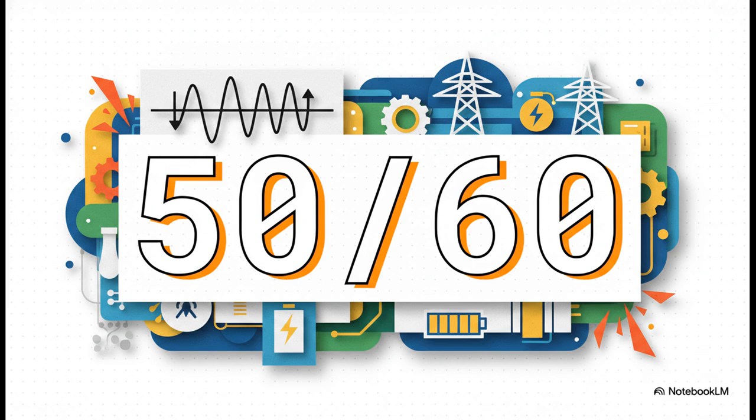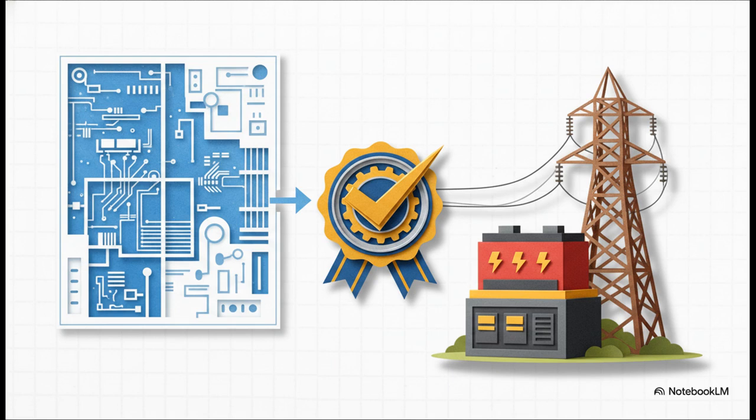The entire Simulink model we're examining today is specifically designed to keep the system locked onto this frequency completely regardless of the external load. To lock in that rock-solid stability, our simulation absolutely has to validate against core IEEE standards. No cutting corners. IEEE 1547 dictates exactly how distributed energy resources talk to the power system interfaces. And IEEE 2030.2.1 provides the literal blueprint for designing and operating the BESS. Ensuring we comply with these means the jump from a digital MATLAB model to a physical, real-world deployment will be seamless and, most importantly, safe.